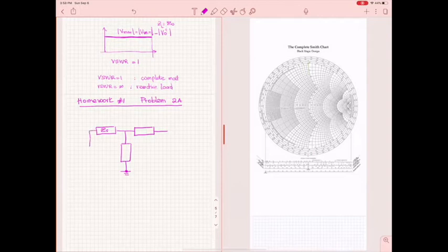So there actually wasn't a Z sub S there. There was a resistive load. The load was on the left-hand side, and the resistor was on the right-hand side. The left-hand side resistor was 50 ohms. And on the right-hand side with the transistor, there was a gamma S equal to 0.5 with the 145-degree angle. Okay, so that's gamma sub S.